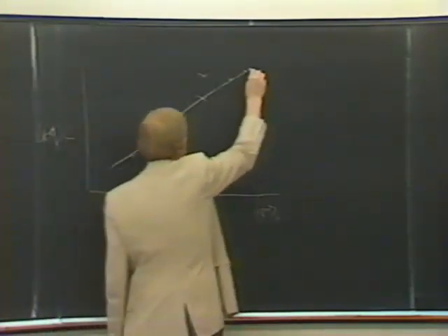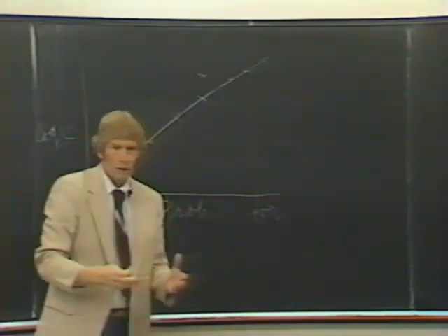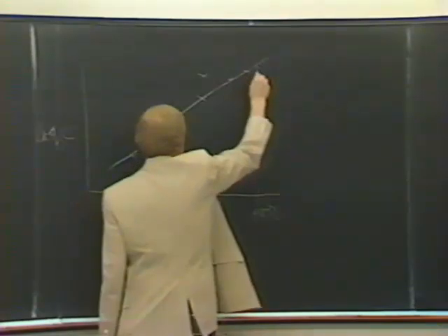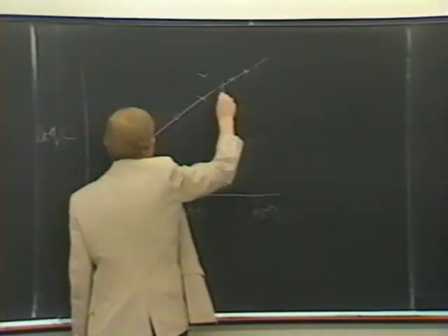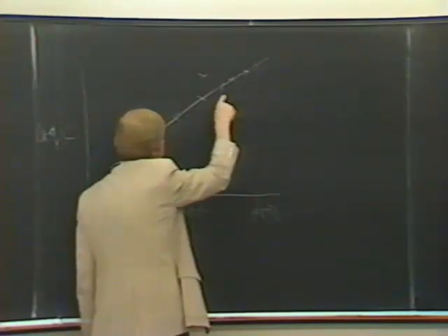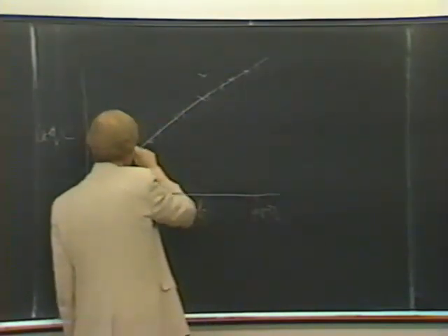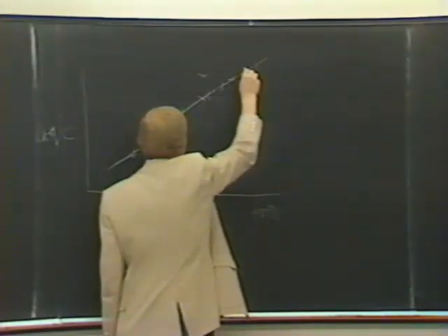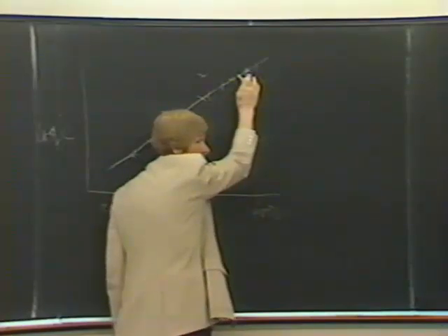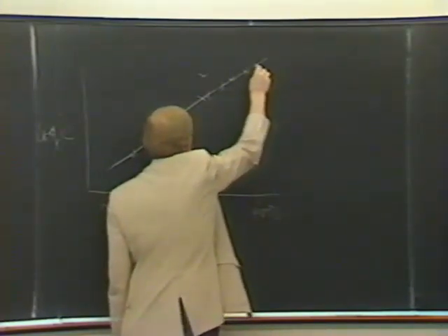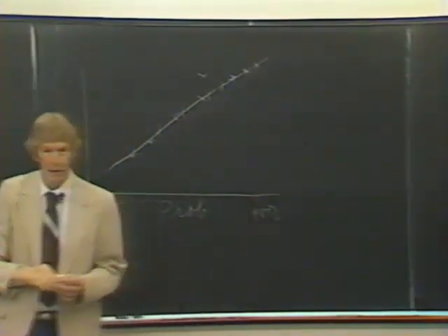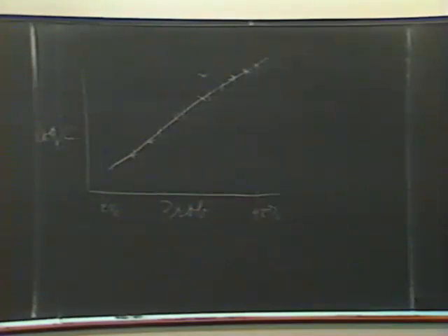Then, recalling that the high concentrations are the ones that bring the most sediment in, what I usually do is break this up into short segments, with wider segments at the lower part, and then calculate the amount of deposition you'd get for each of these at their upper end, and then sum them all up. Now that's a hard way to do it, and it usually doesn't give good results. It usually gives you results on the low side.